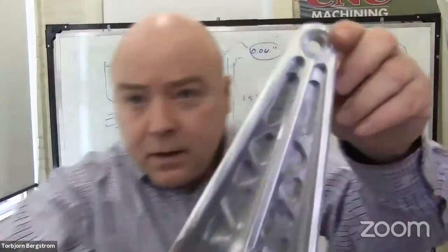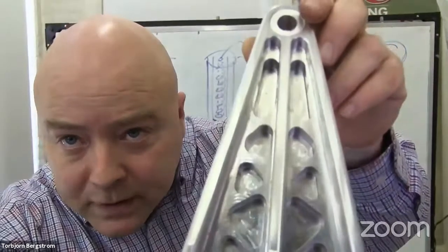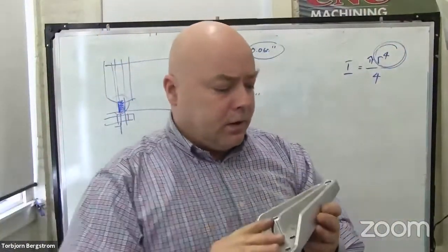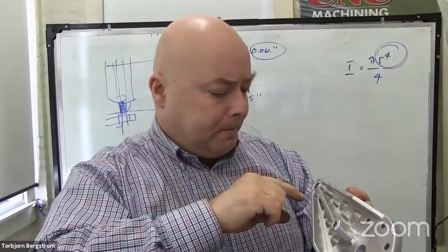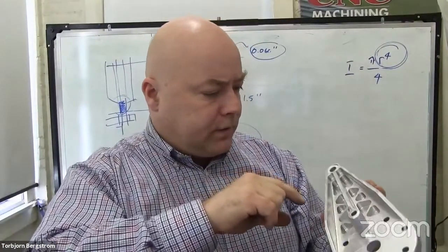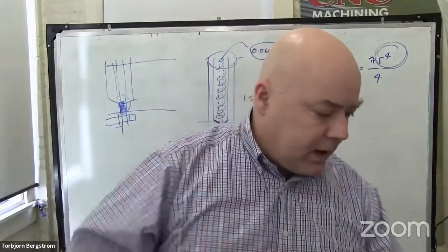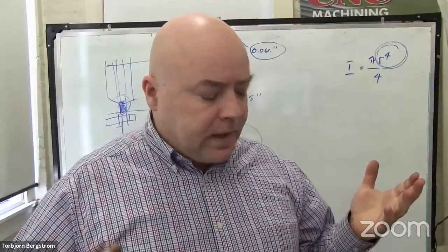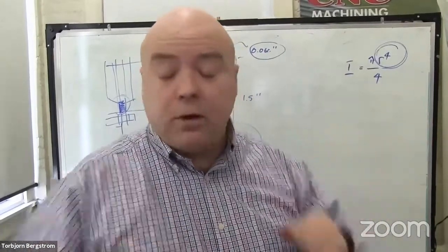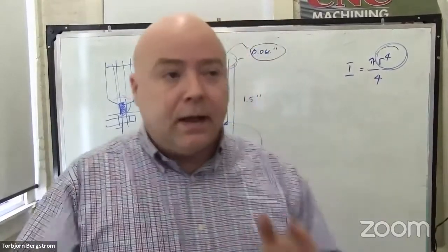Actually, there are these pockets that you see in here. Those were pretty difficult to make because in order to fit the tool in there, it had to have a long reach. And when you have a long reach, if you could see close up, you'd see there's some pretty ugly surface finish on the edges of those pockets. They were only there to remove material to make the part lighter, so it wasn't a big deal. And Paul didn't care. He painted the thing anyway.